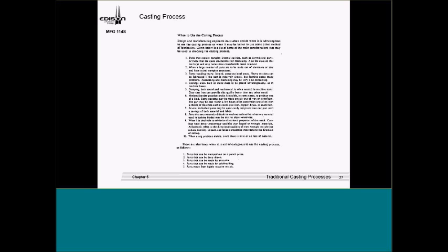It also talks about out here at the bottom that it's not advantageous to use the casting process if you can stamp it out on a punch press, deep draw, and again, we'll see a little bit of pictures of that here after a bit. Extrusions or cold heading, or if you have highly reactive metals.